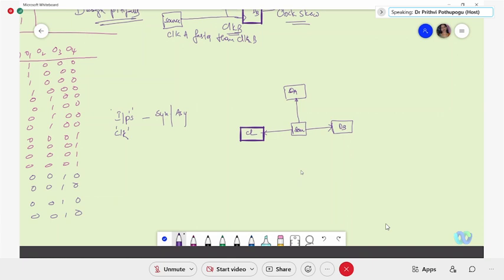The other way is that if this clock source is placed here, isolated, if centralizing this is not possible, you run the clock wiring such that the lengths will be equal. If this is wiring, this is one length, second length, and third length, they are equal length wires. This format or this format, you can avoid the clock skew. This is the practical aspect.